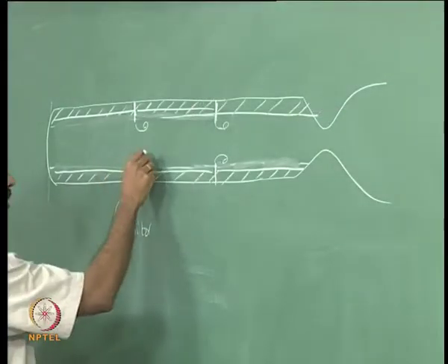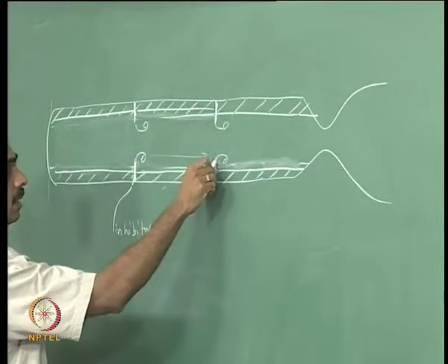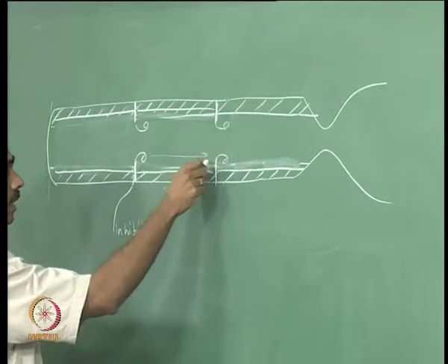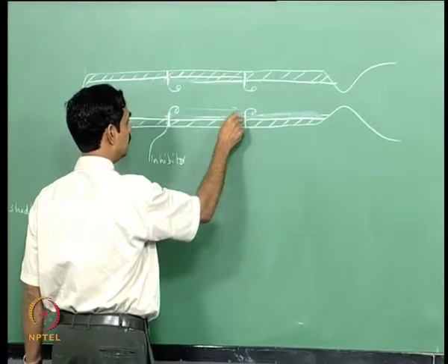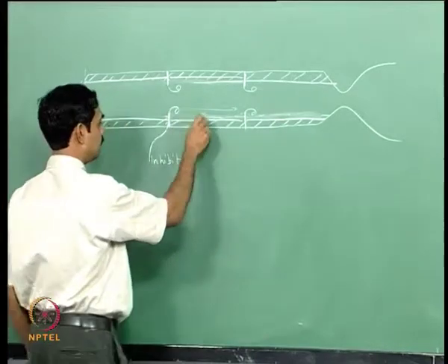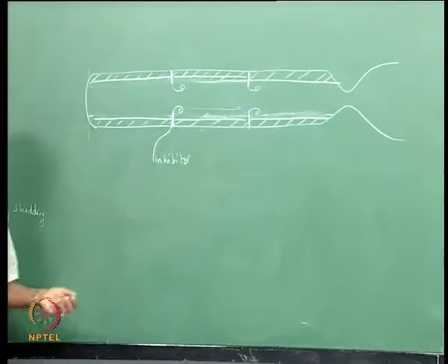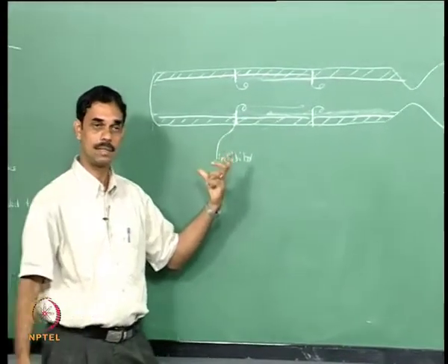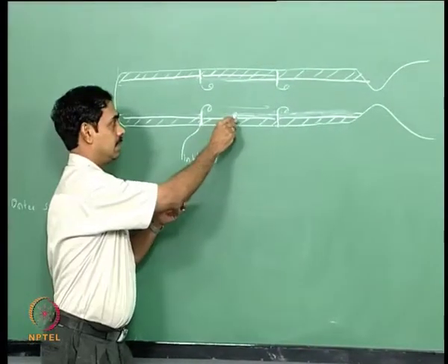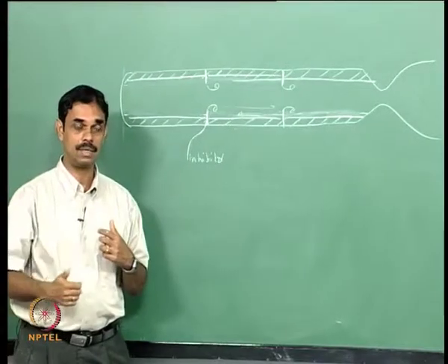This vortex that is shed will come back and come here, and right as it comes here the next one may be shed, and as it impinges here you send the acoustic wave back, and this gets into a feedback. Normally it sheds at some frequency, but when you are under the lock-on circumstance, the acoustic wave reinforces the shedding, and then you get loud amplitudes.